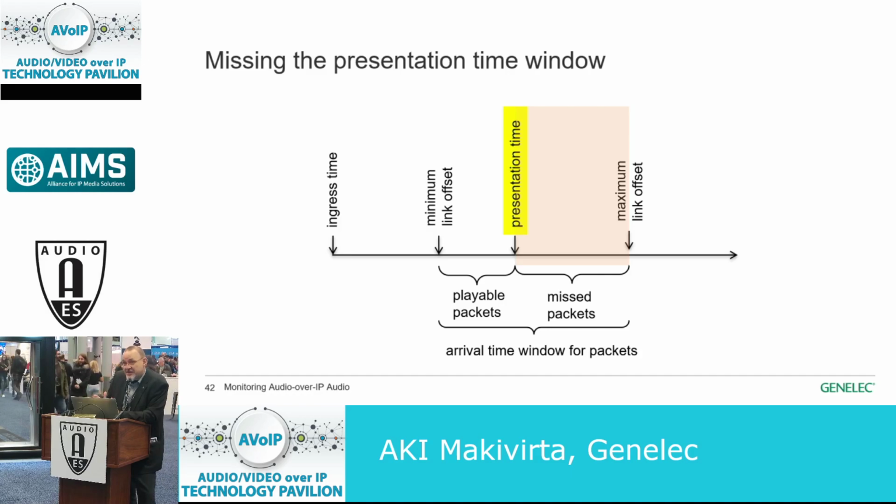So this is the typical reason why people can be frustrated at some point with audio over IP networks, because they get silence out of the network and they wonder why this is happening. This is one of the reasons why this may be happening, because you require the network to be working kind of too well, to be too efficient in delivering the audio to the receiver. In order to deal with this, you have to consider how much audio you stuff in individual packets, because you can only send the packet off to the network when it's full.